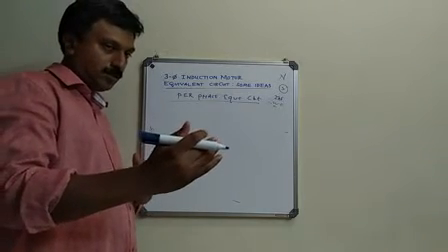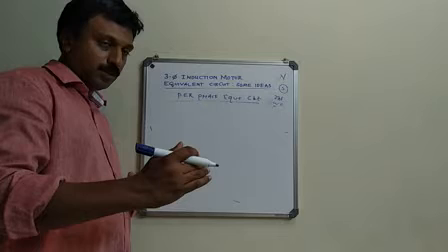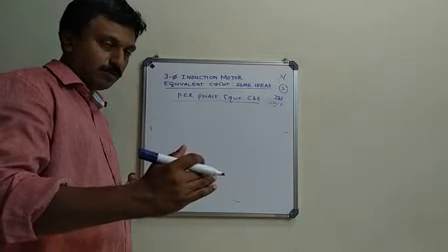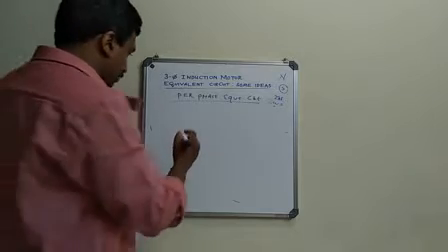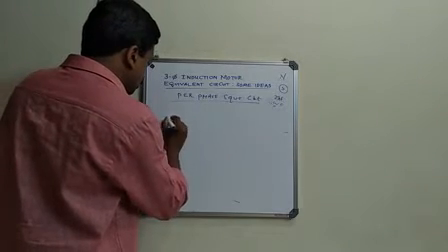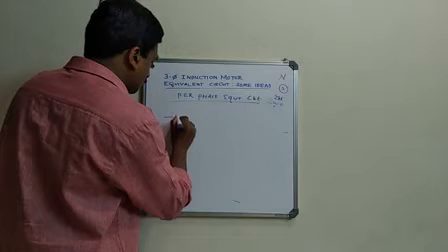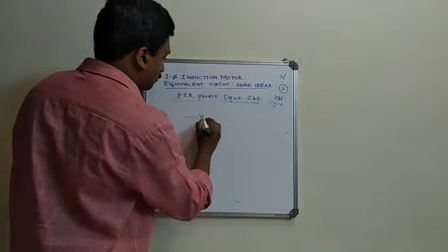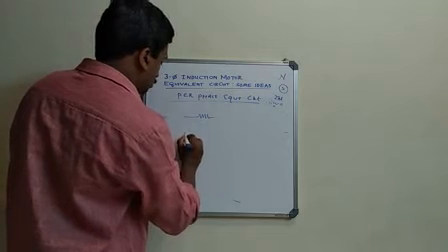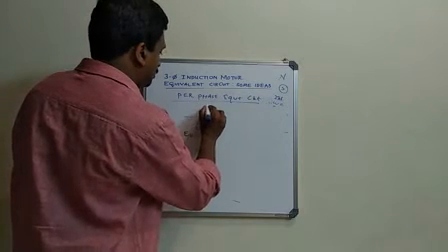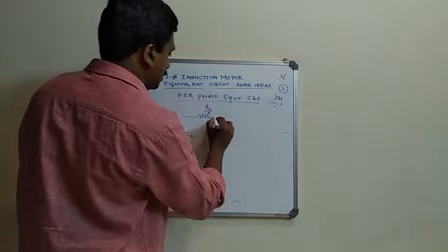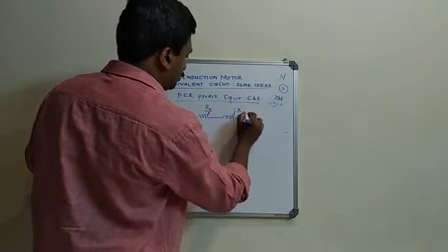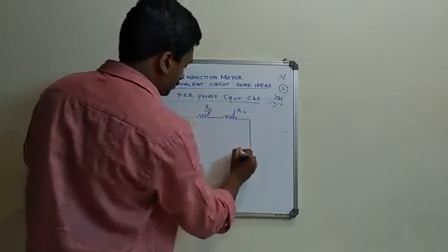This is similar to what we do in the equivalent circuit referred to one side of the transformer. So here, your SE2 becomes E2, this becomes R2 by S, and this is jX2, the leakage reactance.